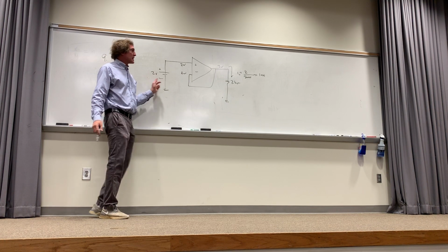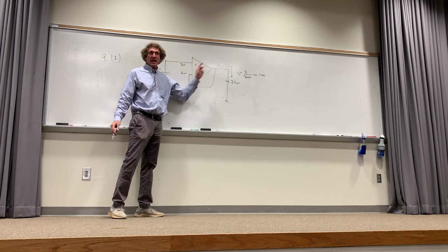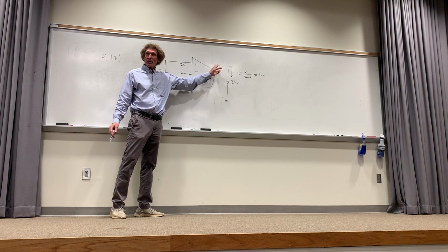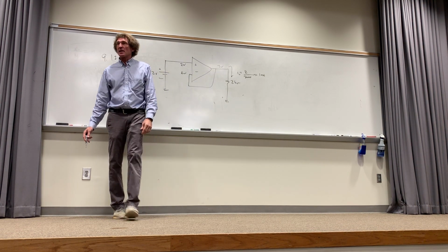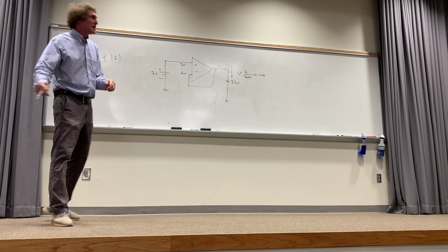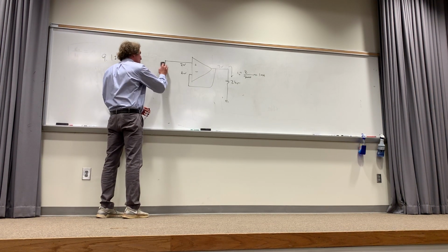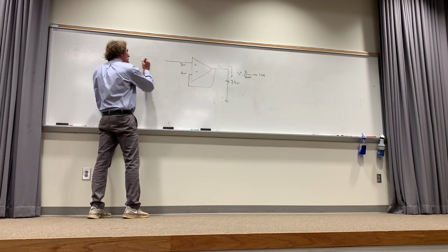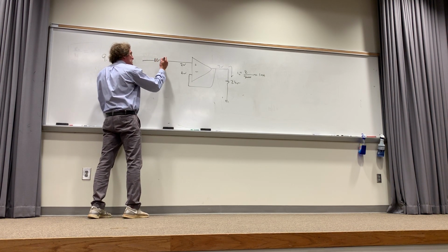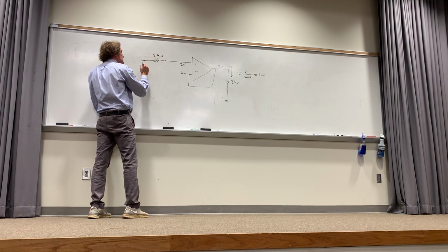But what you end up getting is the same exact voltage as the input, as you wanted here. And then now you have the ability to drive current and power. You can get a lot more power out of it. Because usually this 2-volt source, I'm going to just tell you the real truth about it. What he's trying to do is show you something that's real. Normally with a lot of sensors, they can be modeled as an impedance of maybe 5 mega ohms, and then they're going to have the sensor that creates the voltage. You would have plus or minus 2 volts.